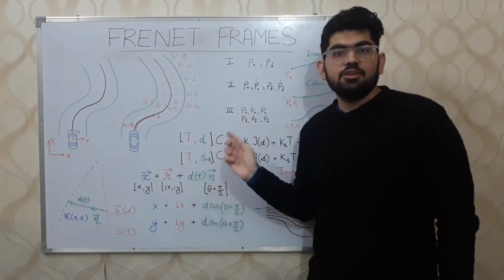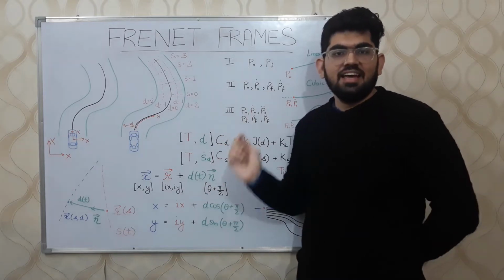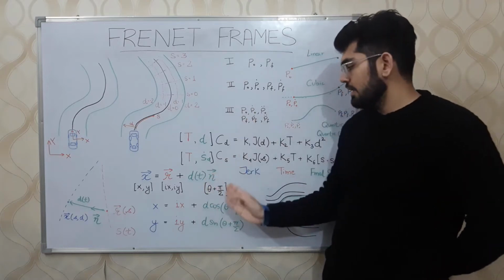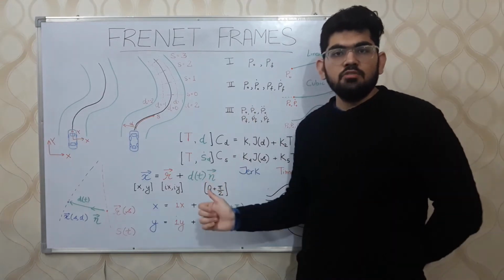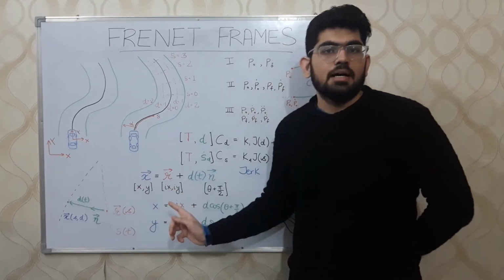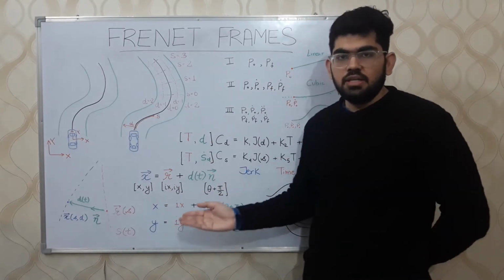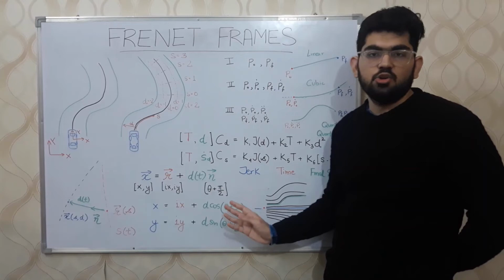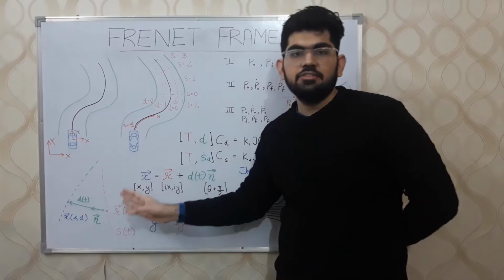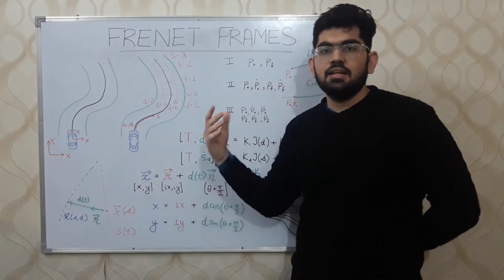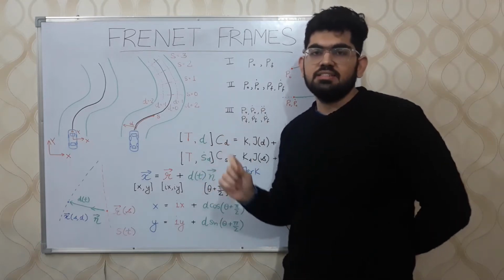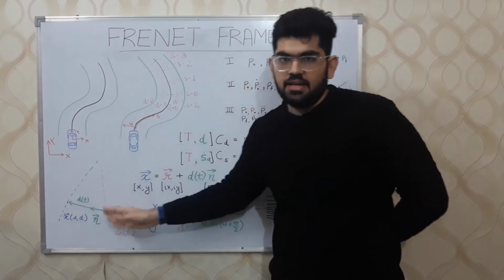The distance d is already a scalar value. Vector n is a unit vector whose direction can be determined using the angle theta plus pi by 2. Theta over here is simply the yaw or the tangent angle of this reference path. The complete relation in 2D can be represented using the equations given over here. Converting from the x and y coordinates to this Frenet frame is also simple. It is just the reverse process of what we have done over here. We simply need to find the smallest distance vector connecting x and r.